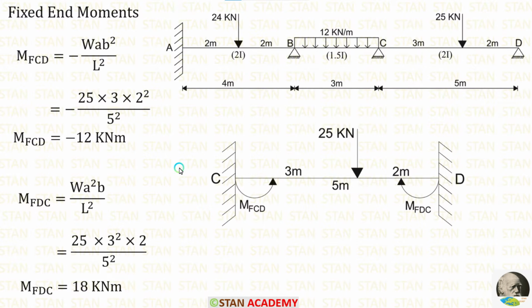Now let us calculate the fixed end moments in the span CD. In the span CD, we are having a point load. This point load is not acting on the center. We have already seen the formulas for the fixed end moments: minus WAB²/L² and positive WA²B/L².